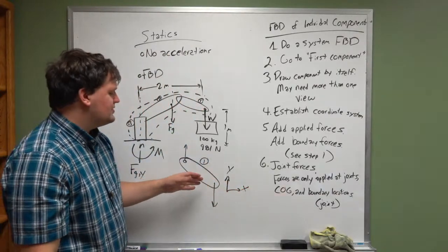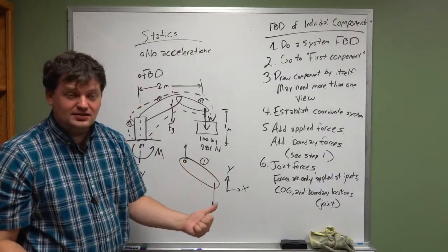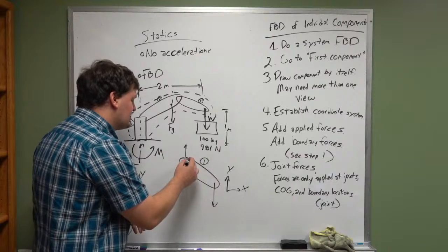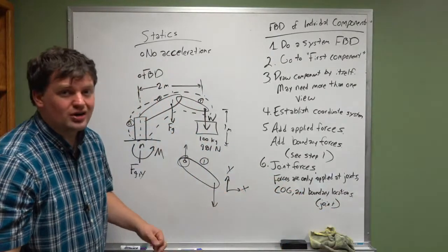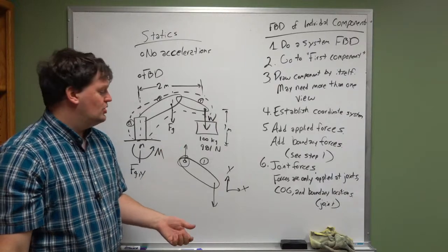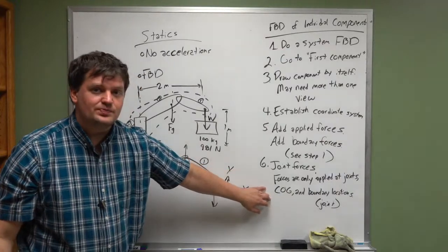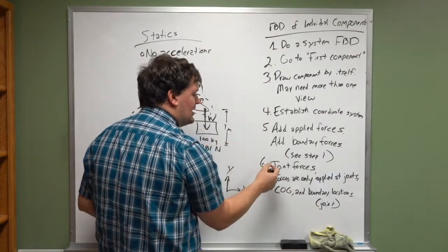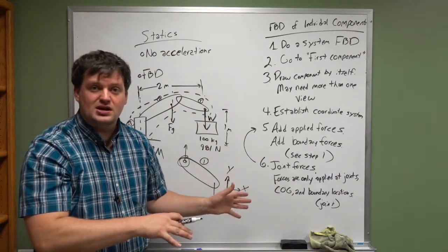When we talk about all of these, you also have to do your force summations for the X, Y, Z directions on your components based on the loading conditions that are given. And you need to figure out what these joint forces are. Figure out what these boundary conditions are on those components that are creating those forces. You have to do that. Once you know what forces are required out of your joints, you then take these joint forces and apply them to the next one. That is, it goes into this step for the next component. Those forces are equal and opposite on the other side.